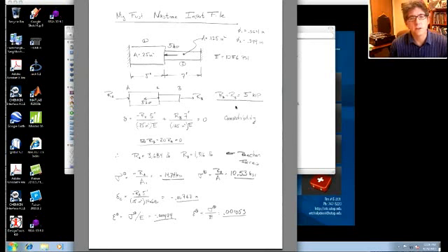So here's just the mechanics of materials type of solution for this problem. It's just a statically indeterminate problem. So we have reaction forces at A and B. They sum to equal the 5 kip force. But it's statically indeterminate. You have two unknowns, one equation of equilibrium.